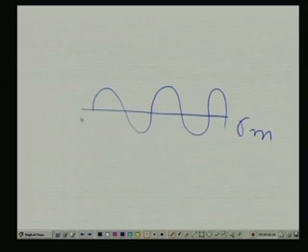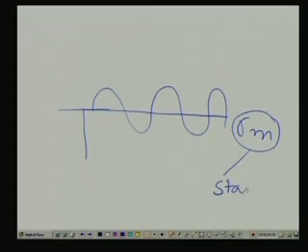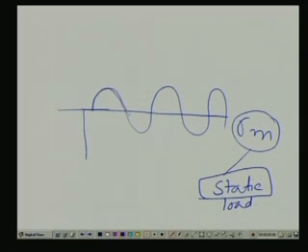If we consider the mean stress, then we consider the design to be static, because mean stress somewhat resembles a static load. Over this you are superimposing the fluctuating stresses, the repeated stresses or the complete reversal stresses. So it is a mean stress over which sigma a, the stress fluctuation, is being superimposed. That is the basic idea of the design.